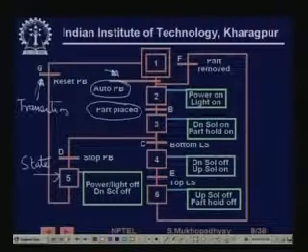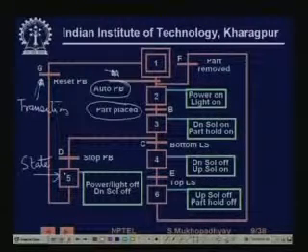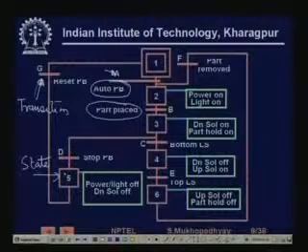It may so happen that, if the stop push button has not been pressed, eventually the bottom limit switch signal will come, and then it will come to state 4, in which it will activate these outputs. On the other hand, if the stop push button is pressed before the bottom limit switch, then it will come to this state where it will simply stop and put the power and light off. So, using a graph of nodes and edges, we can describe the behavior of the system unambiguously.